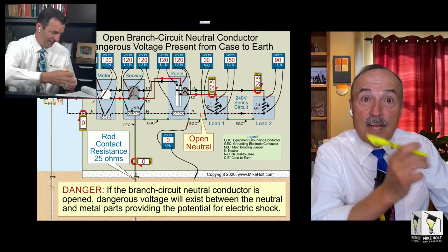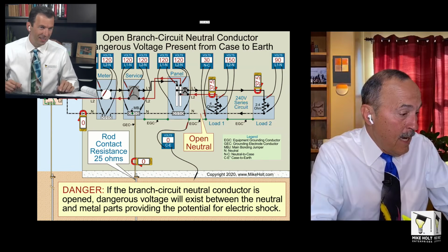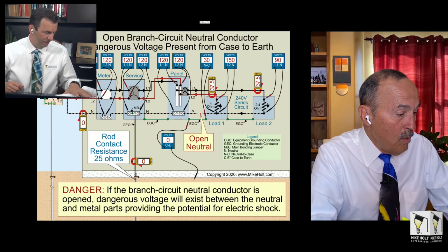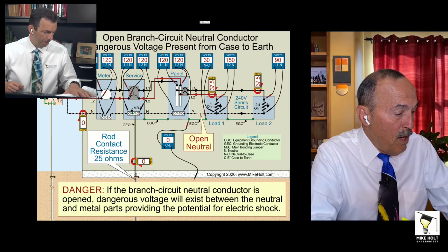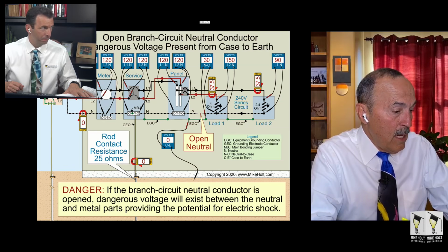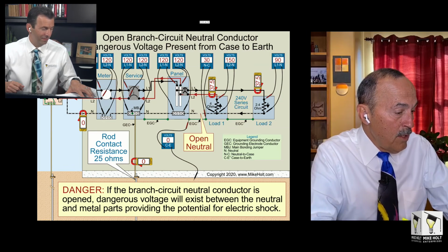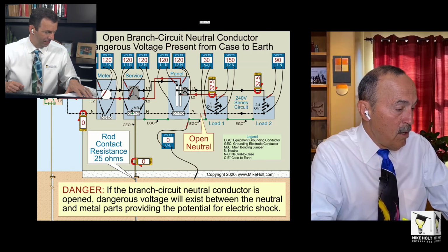You ready for this? As if I didn't say anything before. Handhole enclosure covers shall have an identifying mark or logo that prominently identifies the function of the enclosure, such as electrical. Handhole enclosure covers shall require the use of tools to open, or they shall weigh over 100 pounds.